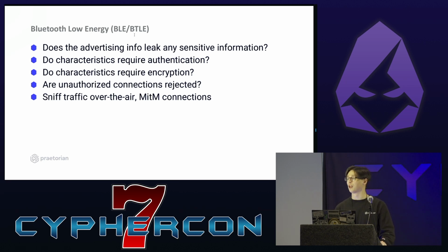If you connect and fail to pair, but the device doesn't boot your connection, it might not start advertising again, so you may be able to stop other people from connecting to the device just by having an open connection hanging. This may seem like a nuisance for a lot of products, but consider a BLE-enabled access control system, like smart locks on an office building. What if you could tie up all of the lock's connections and stop those from having a door be locked, or stop it from being unlocked in the event of an emergency, for example?